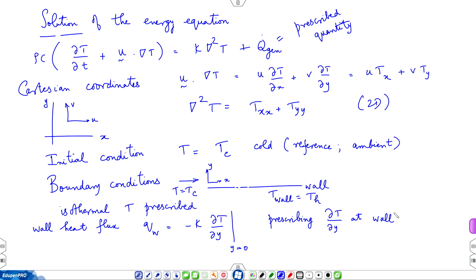Now, what is K? K is thermal conductivity of what? In this problem, we are talking about temperature distribution in the fluid medium. So, this K is the thermal conductivity of the fluid medium above the plate. So, this Q wall is coming from this side and K is of that side. But sometimes we focus on the wall, then of course, K becomes conductivity of the wall. So, you have to be aware of what calculation is in progress. So, I may write here Kf.